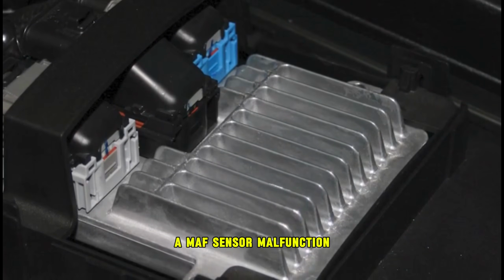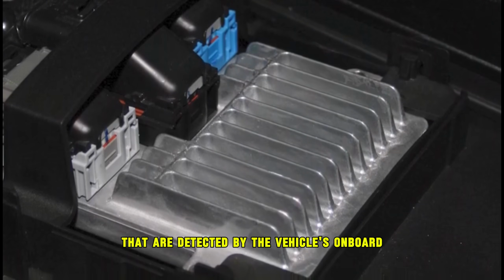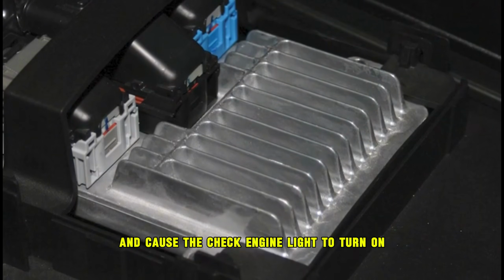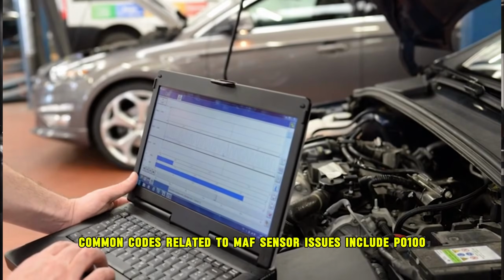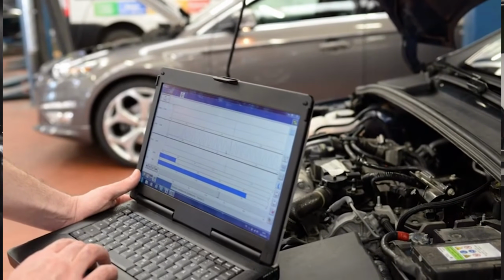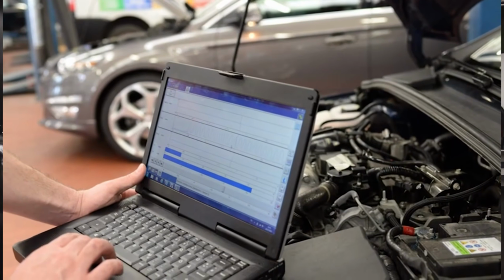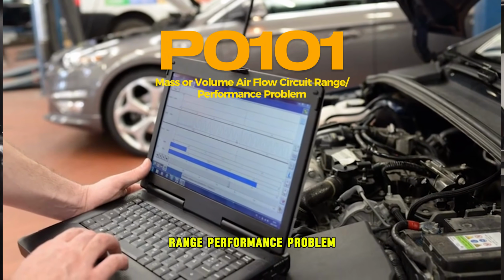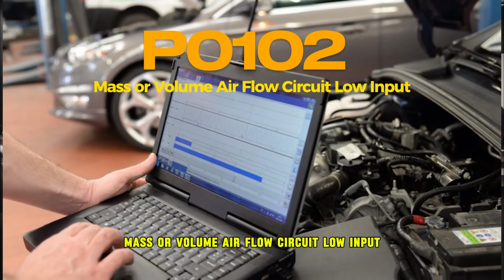A MAF sensor malfunction can generate specific trouble codes that are detected by the vehicle's onboard diagnostic system. These codes are stored in the ECU and cause the check engine light to turn on. Common codes related to MAF sensor issues include P0100, mass or volume air flow circuit malfunction, P0101, mass or volume air flow circuit range, performance problem, and P0102, mass or volume air flow circuit low input.